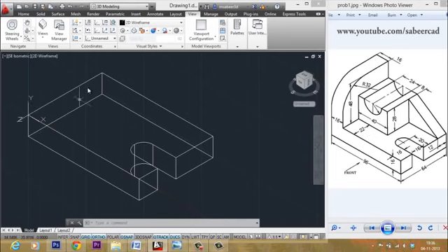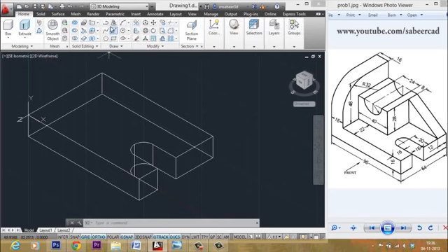Okay, so I'll draw a polyline. You can just go to the Home tab and click on the polyline tool. You have to give the coordinates in absolute values, so I must start with X first. I'll give 16, comma, and Y is 0, 0. And I should give a Z coordinate of minus 22 because it's in the negative Z direction. So you have located this point.